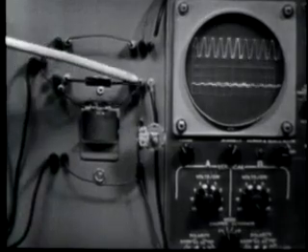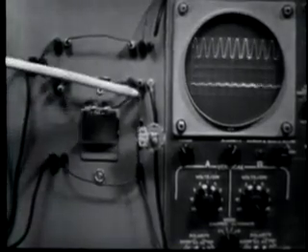Now, as is true of all other filters, reversing the position of the shunt and series components reverses the action of the filter. Let's see. Now, the parallel tank is in the series position. The capacitor here, and across it, or in parallel with it, the inductor. Tank in the series position. In the shunt position, you'll notice that we have our resistor. Now, let's check the frequency response of this circuit.